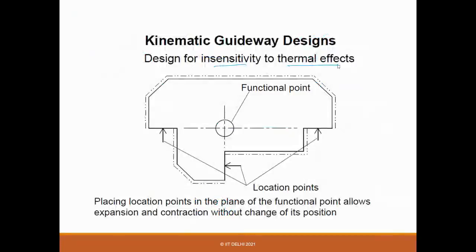In normal cases, if you have any joints, or suppose you have a plate bolted to the base frame, and there is a thermal gradient or heat source, there will be expansion. And if there is no heat source, suppose it's just switching on and off, there will be expansion and then contraction. So there will be a lot of thermal strain, right?